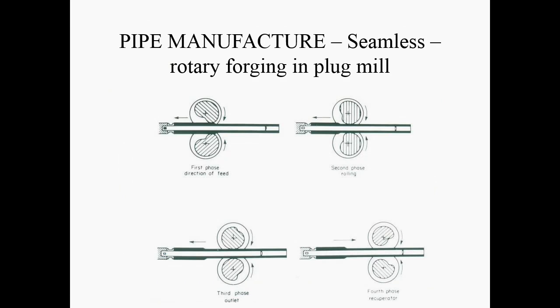First of all, you've got these forging or plug mills. So you can imagine you've got a roller here, and the roller might have some geometry. So this part of the roller's got a narrow gap, and this part's got a wide gap. You can imagine that moving along something, so there's a central filler here, and it's rolling along and it's squeezing this material, but it doesn't go the full length. You let off the pressure when this part here is rotated.